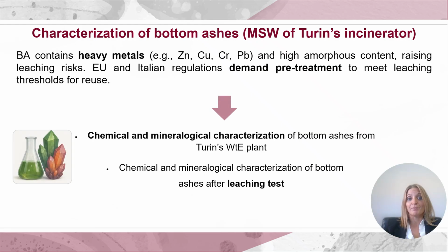Clearly, you can imagine that bottom ashes are not inert. They contain heavy metals like zinc, copper, chromium, and lead, and have a high amorphous content, raising potential leaching risks. European and Italian laws then require a pre-treatment before the reuse to comply with strict leaching limits.